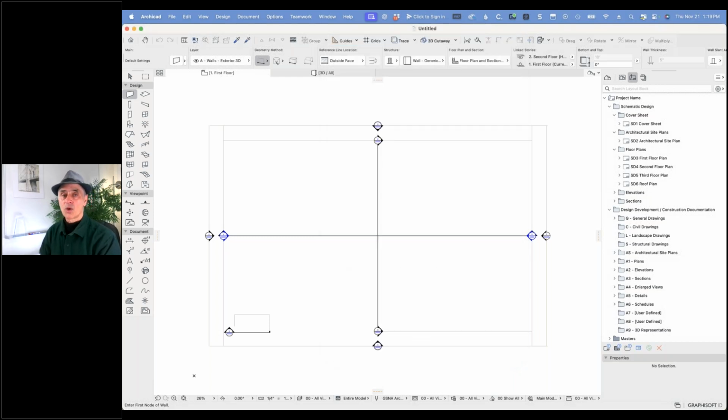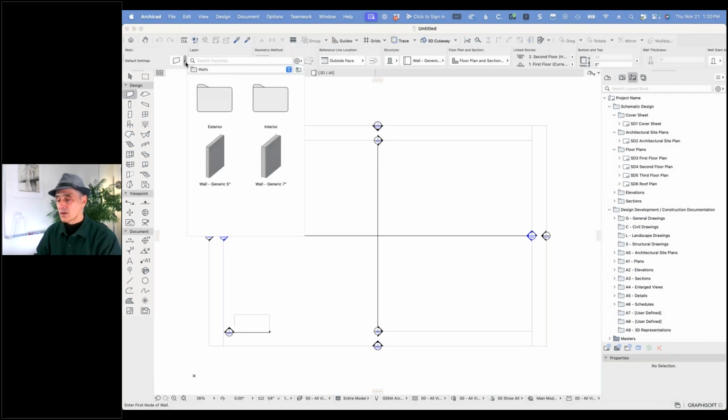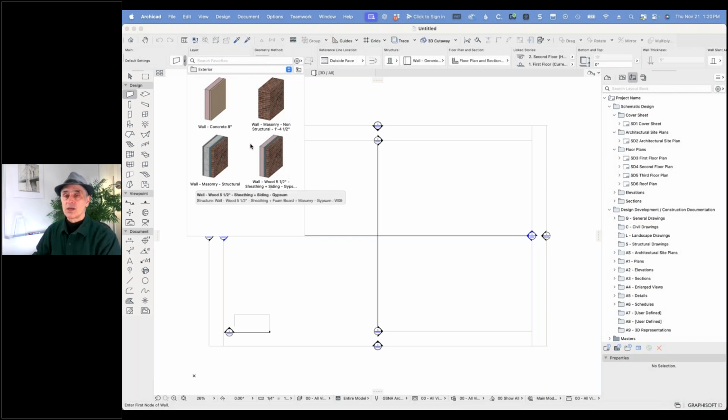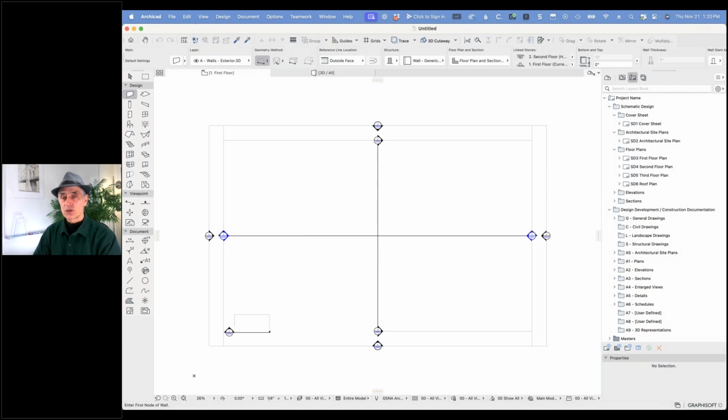So a template includes what's the starting point. Now, of course, for most of these tools, you're going to switch that all the time. So you're going to have favorites. So favorites are, as you probably know, go here saying, I have some favorites. Well, if I'm doing exterior walls, here are some ones that are in this template. So the favorites are built into a template. Of course, you can create new favorites saying, oh, well, they don't have a steel frame, metal framed wall in here, and they don't have this type of wall and that type of wall. Define it in ARCHICAD as a wall type and add it as a favorite, then you can quickly switch. So the idea here is that the template should make it easy for you to draw something reasonable just simply by sketching out a building footprint and partitions and things like that.